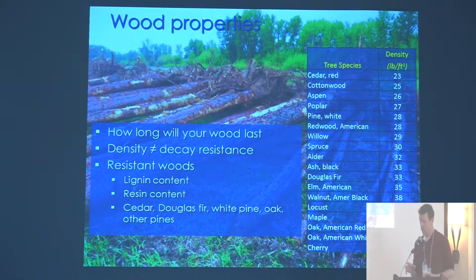But if you're in the Midwest, in an urban area, say, or an area that's wet-dry, you might get 2 or 3 or maybe 5 years out of that cottonwood log, unless the log sprouts up, which I'll talk about in a sec. Lignin content, resin, tannic acid content, these all contribute to the longevity of wood in your system.